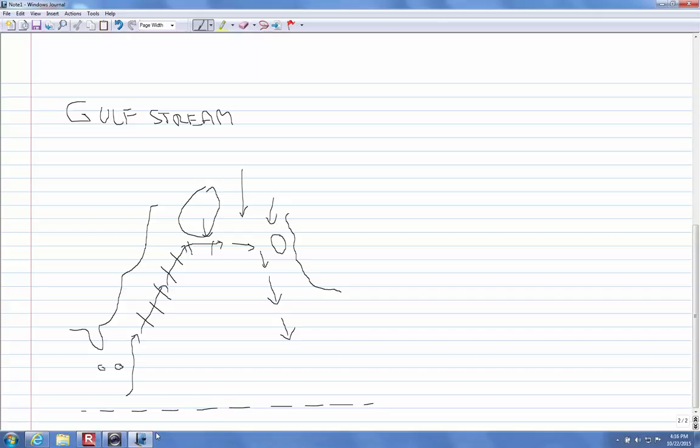And that's a problem with ships, and they use zinc anodes on there. It's a sacrificial anode, so the electricity attacks that zinc, which is softer, instead of the steel. But even then, you still have damage. So you've got that. You've got sea growth that's going to grow on this thing, even though it's moving parts.